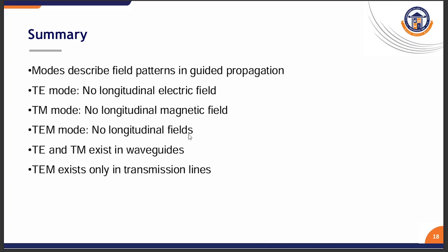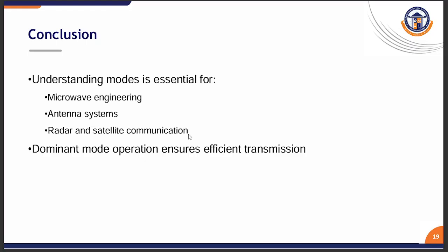So, as a summary, TE mode has no longitudinal electric field. TM mode does not have a longitudinal magnetic field. TEM mode has no longitudinal fields. TE and TM exist in waveguides. TEM exists only in transmission lines.